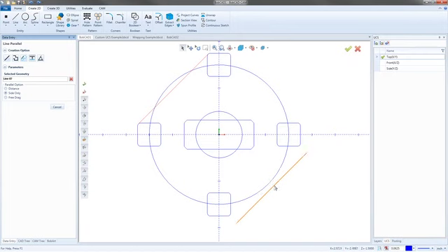So if you're just trying to sketch something, I use this a lot for constructing some sort of box around a part that I may need to make, just a box around the part. I can start out with one line, drag it over side only. That way they stay parallel at the top and bottom. So I just have to draw a line between the top and bottom and work with it that way. And then again, just like the other one, to actually create it, you just have to click, and there it is.